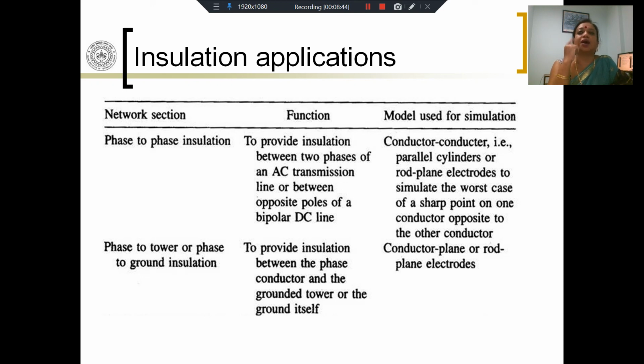We've not talked about partial discharges in general, which we will discuss later in a different chapter, but we have talked about only one kind of partial discharge, that is the partial discharge that takes place in air, which we are interested in when we are talking about transmission lines, because we very often see this in transmission lines. That is corona. We've talked about the different modes of corona when you have a positive polarity high voltage electrode and a negative polarity high voltage electrode. We've talked of the different mechanisms by which breakdown progresses for positive polarity or negative polarity.